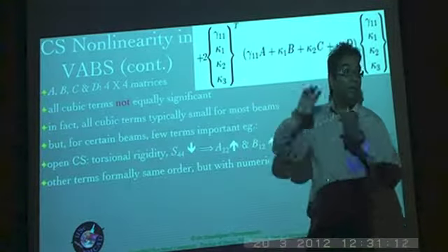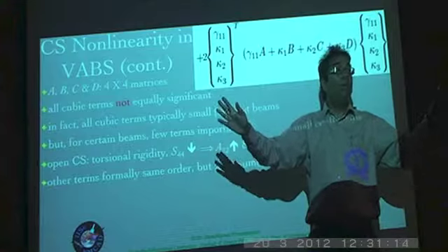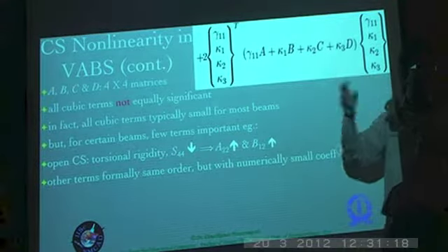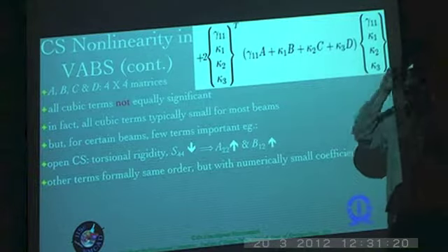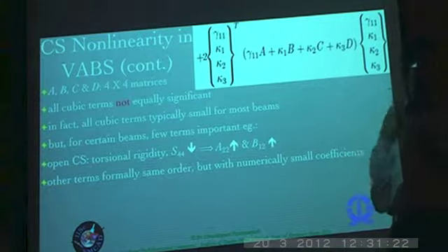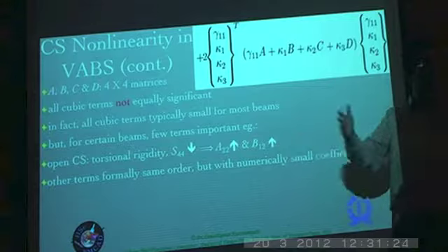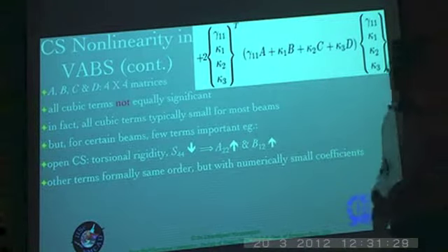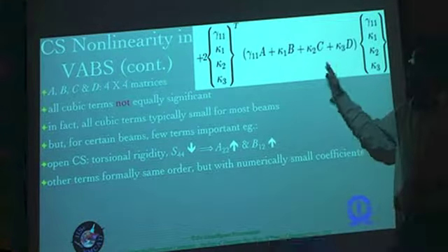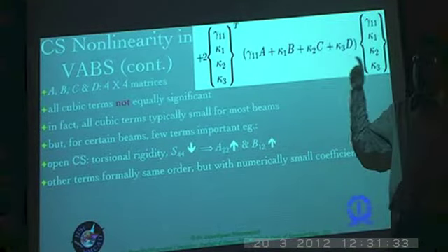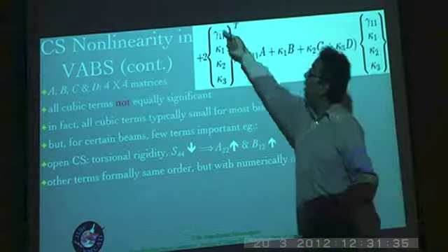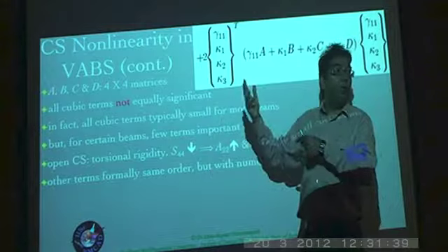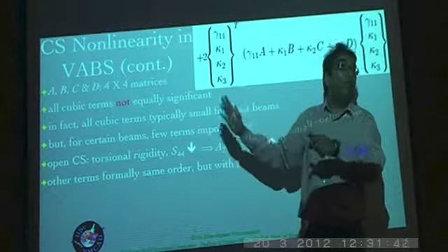By multiplying all of these, what is the expression you get? That has to always be the same. But how you actually manipulate these A, B, C, D, these individual terms, and which element has to get how much, etc., it's all up to you according to the convenience of your derivation or implementation of the derivation in a numerical sense. So what is really significant is, in terms of the strains, the 1D strains, which couples what, up to what power, and how much it contributes to the energy. That's all that is really significant.